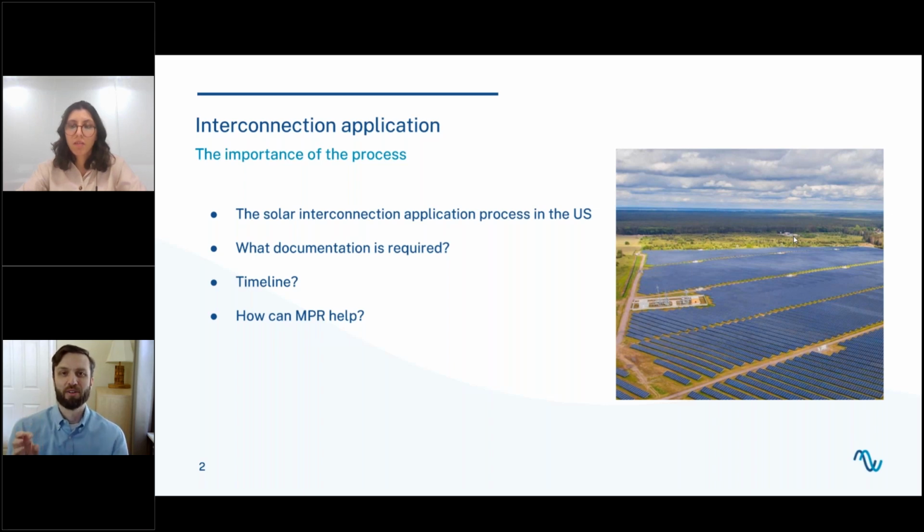Now I want to focus on the collector system equivalent impedance data. That's things like the positive and zero sequence resistance, reactance, and susceptance. Now, those pieces of information are pretty hard to come by, and you have to do a whole bunch of calculations in order to figure those out.